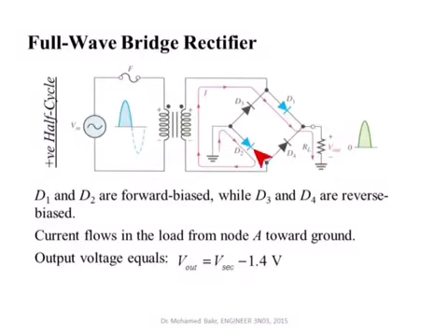And the voltage here at this point is 15 minus 0.7 minus the voltage drop across the resistor minus another 0.7. Okay? Now, these two other diodes, D3 and D4, will be off at this stage. Why? Let's take a look.